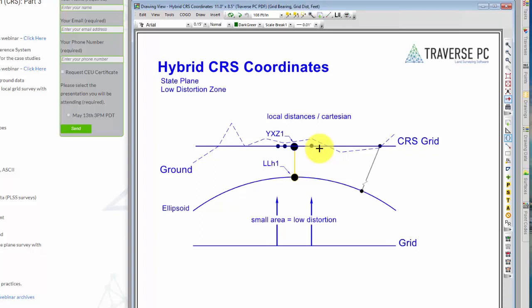Or if I have time today, I'll show it to you, but I'm guessing we probably won't. We could also just think in terms of a local grid or a Cartesian grid at state plane coordinates. Everything we do, we'll do in local grid computations, but if we're not moving too far away from this normal point, our errors are pretty small. So we'll continue just to work in Cartesian coordinates, and those positions can go right back out to GPS, GNSS, Google Earth, whatever, with very little geodetic error in them.